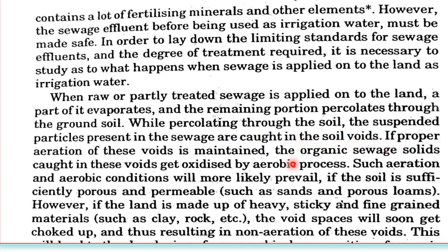If proper aeration of these voids is maintained, the organic sewage solids caught in these voids get oxidized by the aerobic process. Such aeration and aerobic conditions will likely prevail if the soil is sufficiently porous.